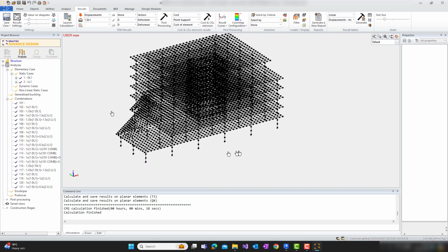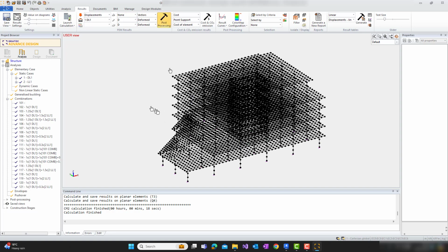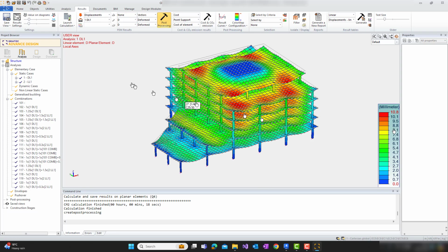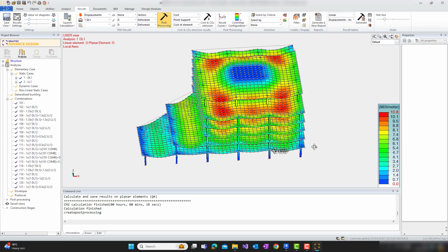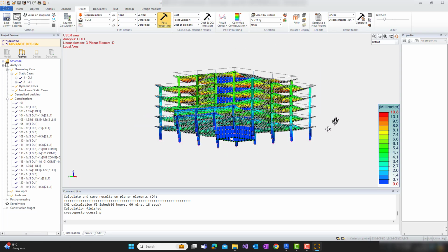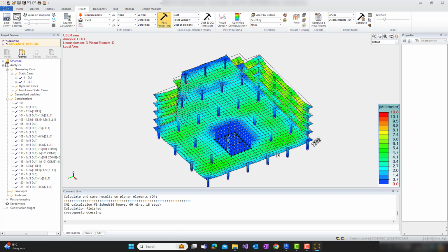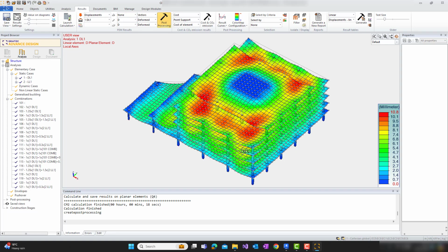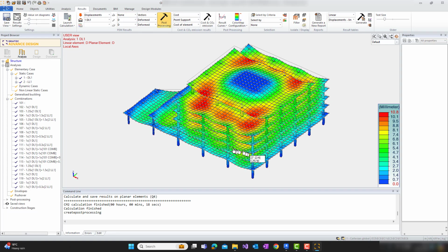We can now look at the displacements. It'll generate the displacements in here now. Just give it a second. There we go. Obviously it'll be quite exaggerated so you can see where the points are. I can already see straight away that maybe putting a beam structure under these slabs might be a good idea, but that's what we can do when we're generating, and we can see what's going on now, and we can start to look at how we can redesign that.